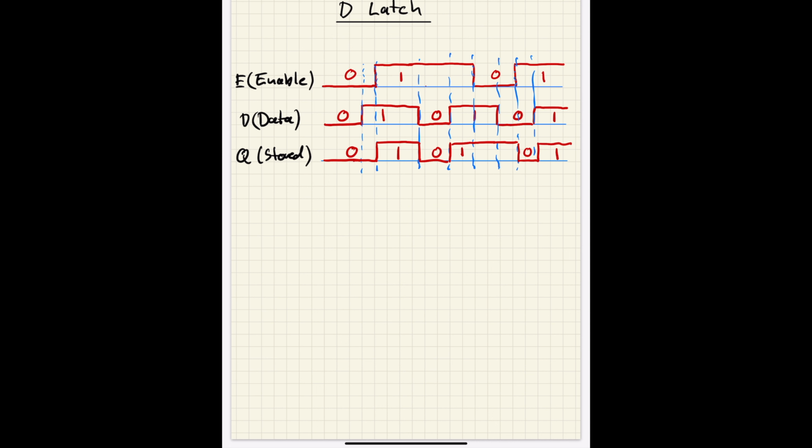And if you would use actual electronic circuits, then with an oscilloscope, you actually could observe what you see here. And there you actually would see the truth that when we change here, for example, from 0 to 1, this doesn't happen instantly. It happens over time. You actually don't see here a straight line, so this might be different, but you see that somehow this change takes some time. But let's keep it simple for now. Let's assume we don't care about these delays.